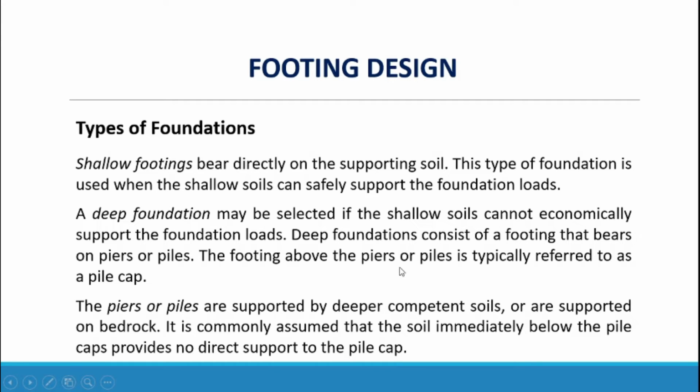The footing above the piers or piles is typically referred to as a pile cap, and the piers or piles are supported by the deeper competent soils or are supported on bedrock. It is commonly assumed that the soil immediately below the pile caps provides no direct support to the pile cap.